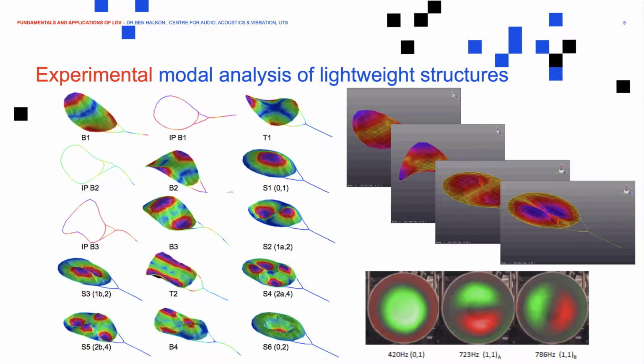So these are the first measurements that have been made of string bed vibrations in 3 dimensions. Again, the orthogonal string bed mode for that vibration mode. In-plane bending is interesting because the hypothesis is that the string bed, in the string bed mode, might drive the frame, and it's the frame that can generate sound pressure. Meshes, as is the nature of the string bed, can't generate any sound pressure, but like a guitar, if the string vibrates, it drives the structure around it, and that makes the pressure that we hear when we strike the ball, well or indeed badly.